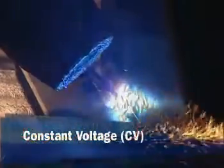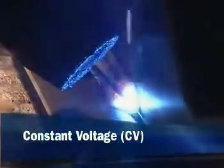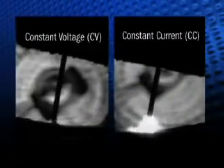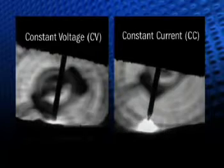CV welding typically allows short circuits in the arc. The shorter arc lengths attainable in CV meant faster travel speeds for manufacturing. AccuPulse and its variations allow the combination of spatter control and faster welding travel speeds by using both CC and CV in the same pulsed waveform. Let's look at how the CC and CV waveforms work together.